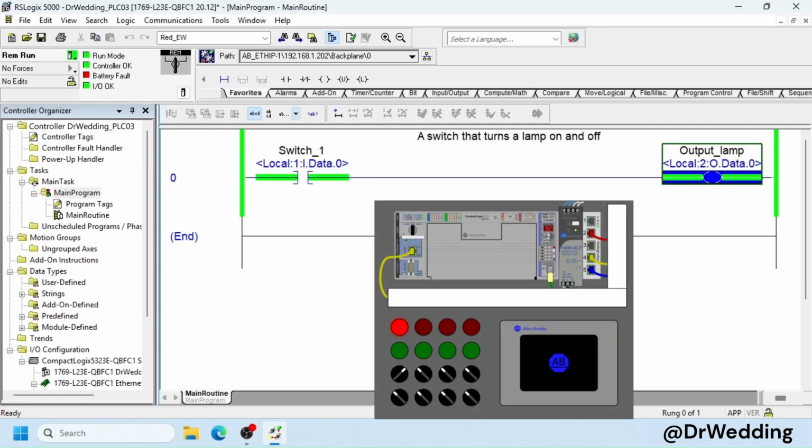When the system entered run mode, the switch was in the on position, so the lamp immediately turned on. This is what the warning message said would happen. If this was a moving object, instead of a light, someone might have been hurt. You should also notice that when the switch is on, the switch turns green. The lamp also turns green, letting you know it is on. When I throw the toggle switch, the light will go out and the green indicators on the rung will disappear. The system is running as designed, and the information from the panel is also showing up on the rung.